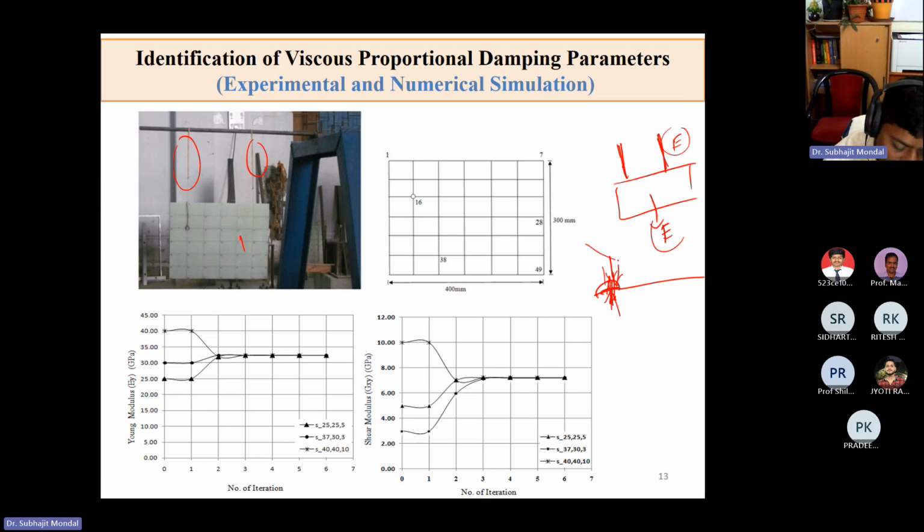So if you go for dynamic analysis in your laboratory for your research, you should go for either free conditions, fixed conditions, or cantilever conditions. This way you can have good accuracy in your experimental data. In fixed conditions we do not have any other motions, that means acceleration along the x direction, y direction, and z direction are all zero, so we do not have any other assumptions. In simply supported conditions, we have to assume that it is fixed only in the vertical direction and can slide in the other direction, but it is very difficult to achieve practically.